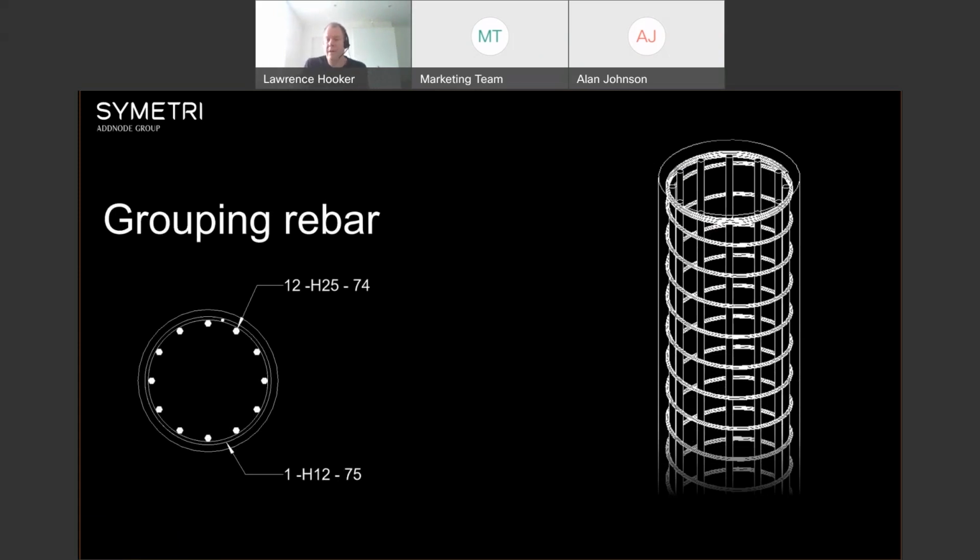So using the method here, which is actually using the freeform rebar, we can actually place in that reinforcement bar as a set. And of course, then you can see that when we called it up, Revit will know that there's 12 bars in there. The other key thing, of course, is because it's a set, I can then just go back and say, well, actually now I want 10 bars or 8 bars, whatever that might be.